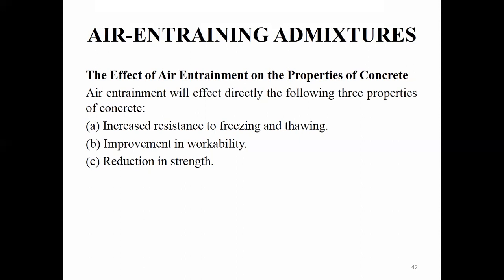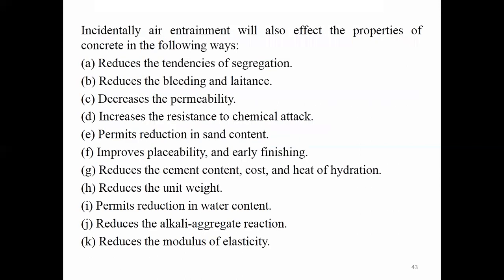So we don't need to doubt whether we can use this air entrained concrete in the normal zone. It can be used in construction also. Next, in addition to this, we will discuss points like segregation, bleeding, and laitance. Since the workability of the concrete is increasing, obviously the segregation, bleeding, and laitance will also get reduced. We have discussed this.